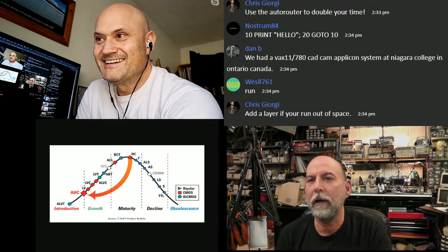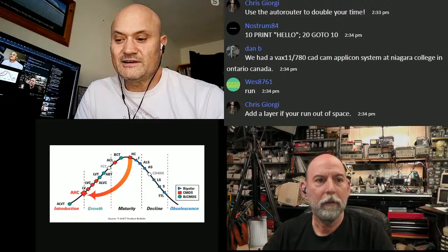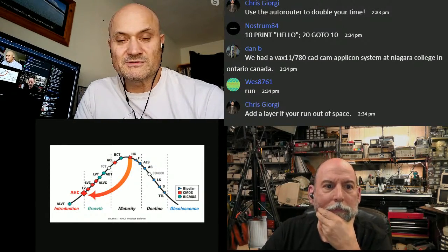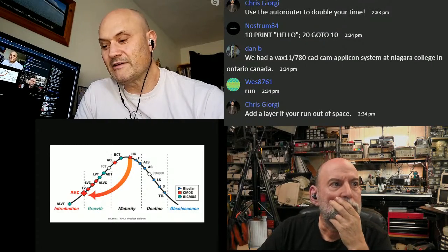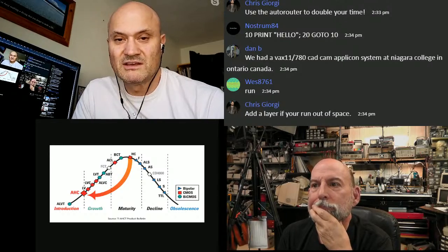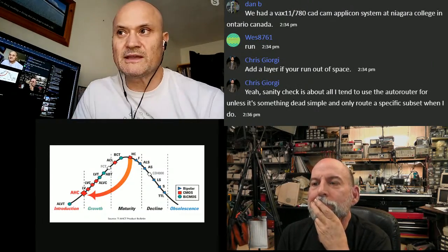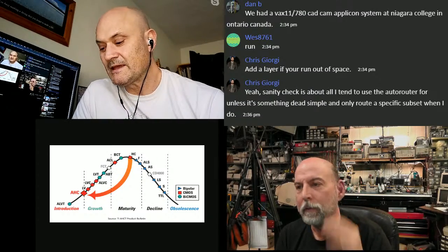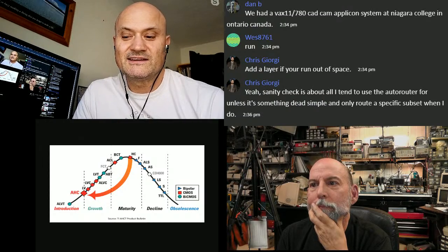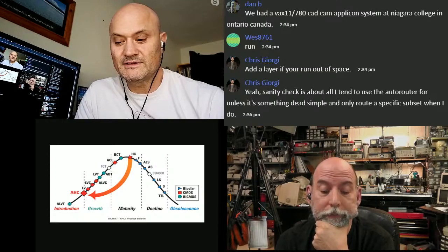As to what I can route, at least. Yeah, so that's the other point. I could auto route something. I've got 4 layers, so I've got some unbroken ground planes. I might route all the power and ground first and fan out first, and then just auto route everything else, and then gloss everything up, move a few things here and there, make it look a bit better. But if I can get to 98% doing that, why spend extra time if you don't need to?